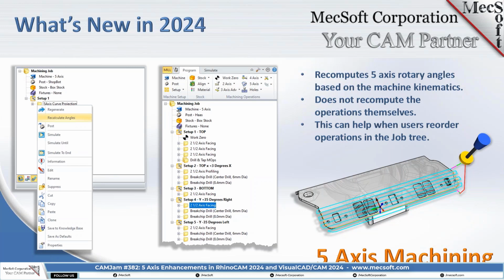So imagine this: if you're machining something and then you retract from the last toolpath position on an operation, in 5-axis mode the angles of the machine tool will be in a certain configuration. Then if you want to start the next operation, the next operation needs to understand where the machine tool angles were set at the end of the previous operation.